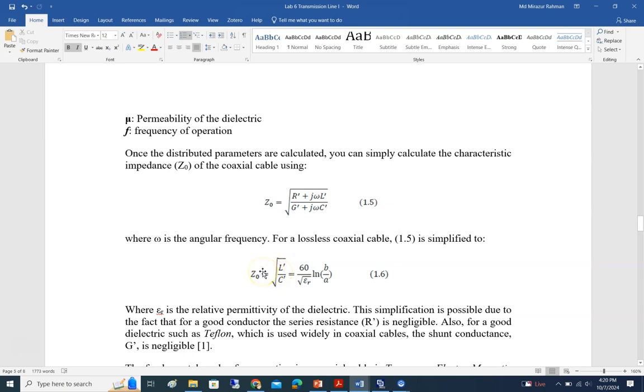If you look at this equation, you see the relationship between Z0 and B and A. You are given epsilon R, which is 2.1. You are given A, but you are not given B. So that means B is an unknown variable, which I mentioned before, that B is something that you have to measure, calculate or determine, so that you can use that in the CST.